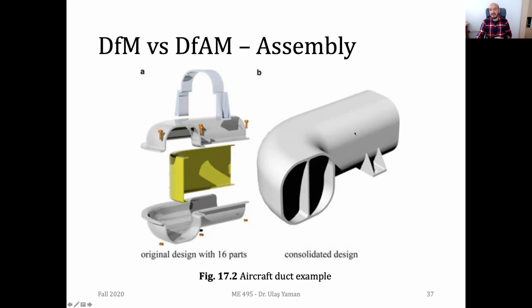But on additive manufacturing machinery, in most of them, you can only produce one kind of material. Right now, we don't have a machine which is capable of printing polymer and metal at the same time. Since the temperatures are highly different with metals and with polymers, it's not possible. But if the material is not important for you, then additive manufacturing might be advantageous.